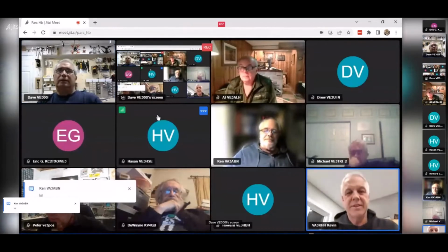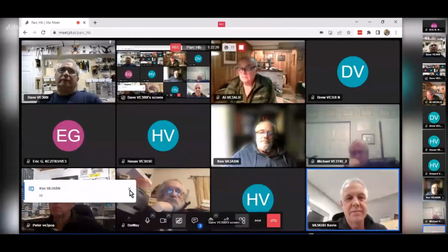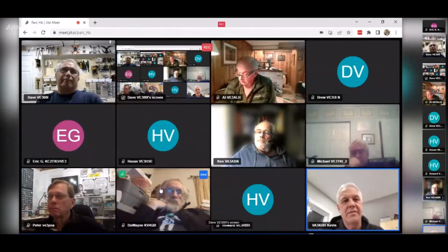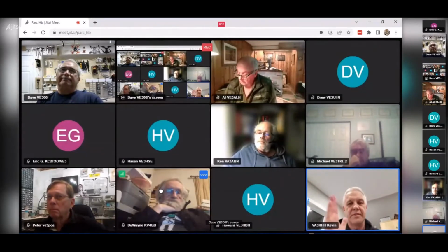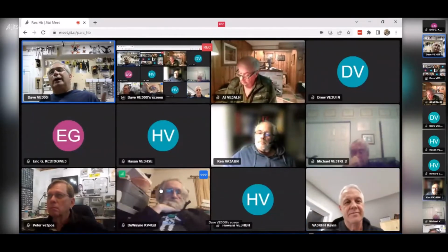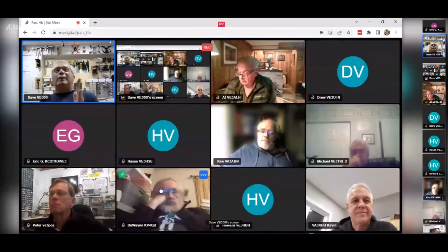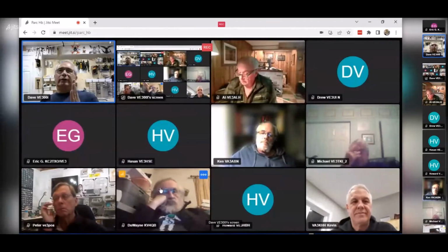Yeah. But couldn't you linearize it by taking your error and dividing it, or doing a trig function on it, like sine or cosine? Because you don't need much gain when you're vertical, right? You need a lot more gain when you're way down. Right, and that's where the trick is. That's why my PID controller worked, because I used more of a linear approximation, and that's why I was able to balance.